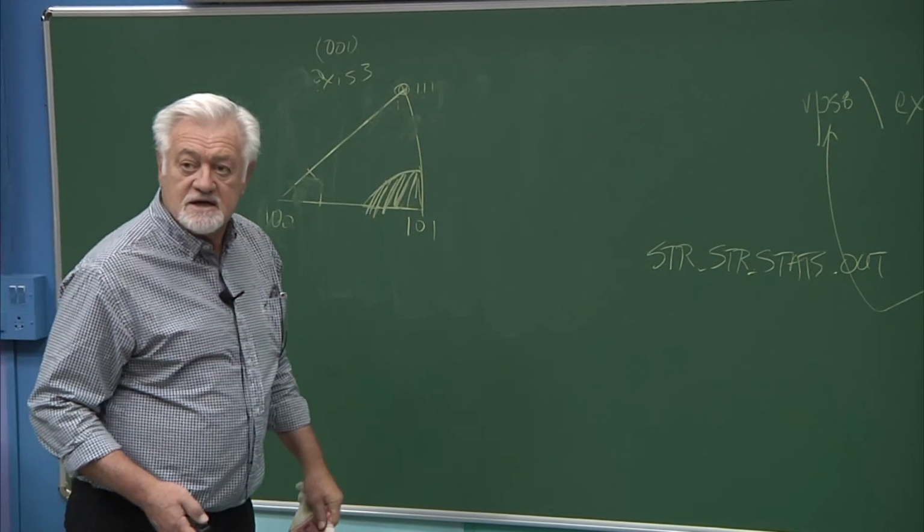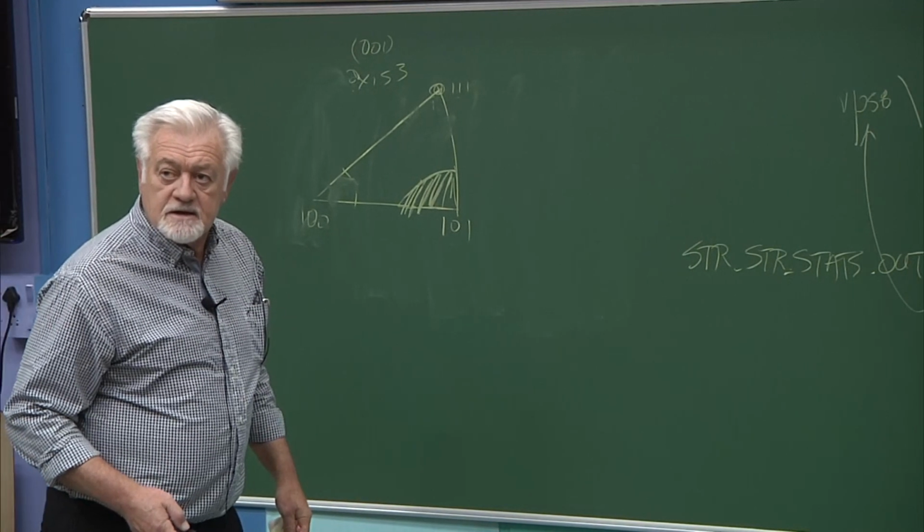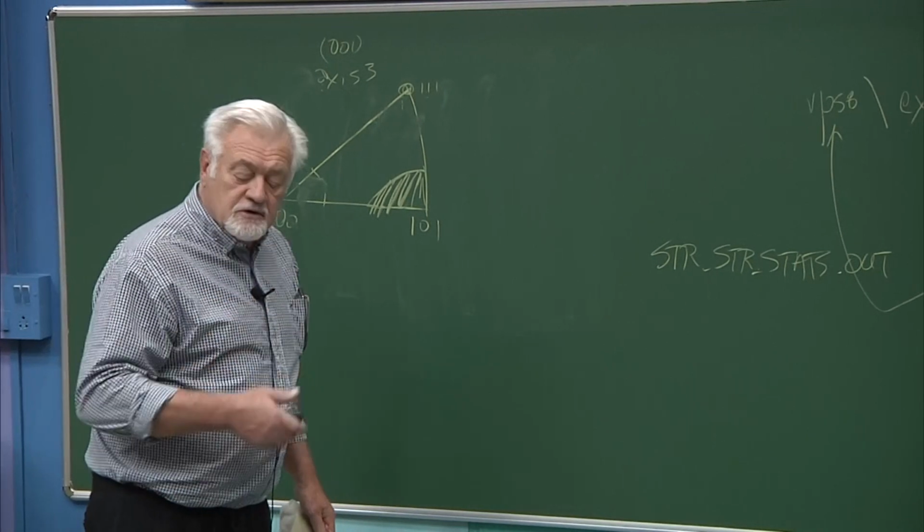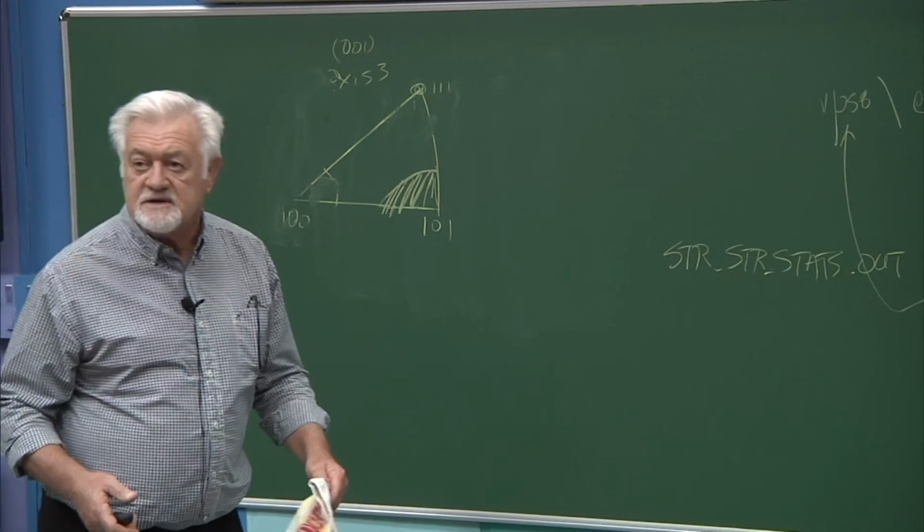Only that. And in the pole figure, when we look at it, that 111 is like a donut. Correct. It has a cylindrical symmetry. Yes. And from this, we can tell at what angle to the loading, to the axis of the sample, the 111 is oriented.